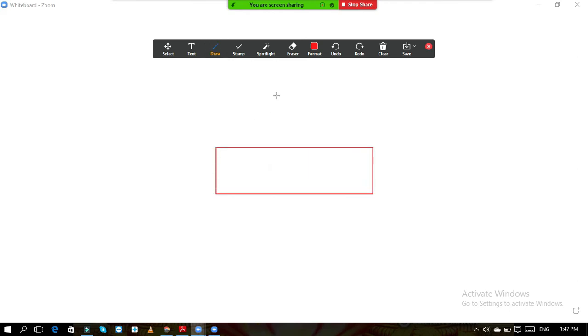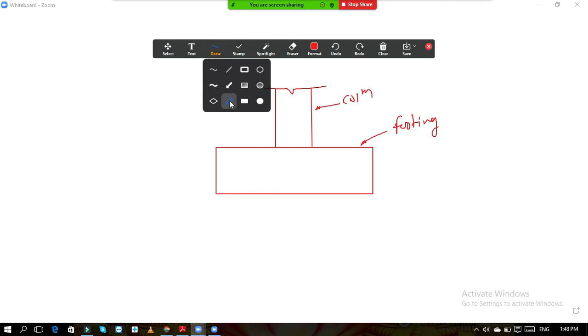So these are the columns. This is the column. Okay. So this is your column, and this is footing. Footing. Now what was your depth? This is your overall depth, and this depth is 520 mm.